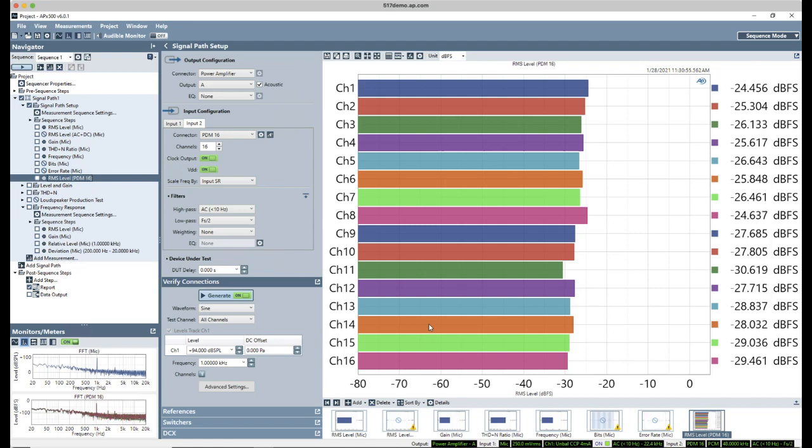And this is quite useful because since I have calibrated my source speaker at the reference position, so at the reference position I have a sound pressure of 94 dBSPL, I can actually read the sensitivity right here. I've got minus 24 dBFS, and I happen to know that the sound source is 1 Pascal. So this is minus 24 dBFS per Pascal.